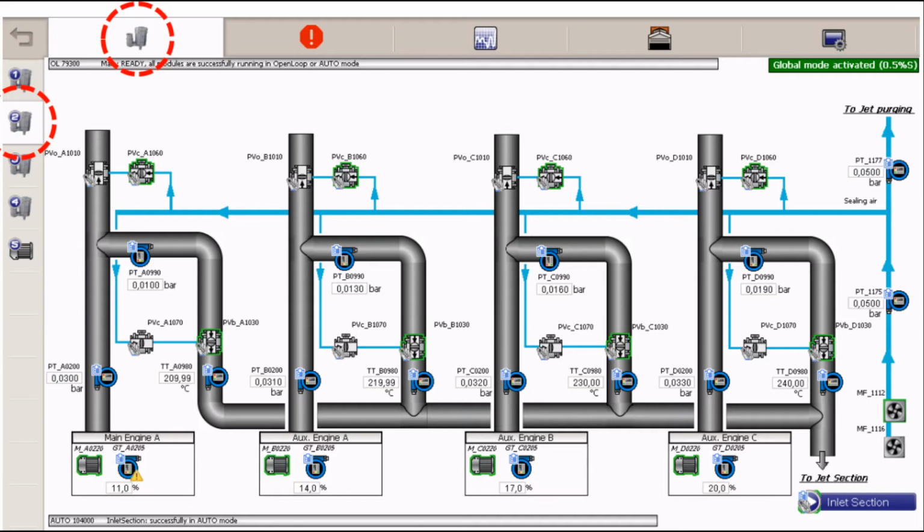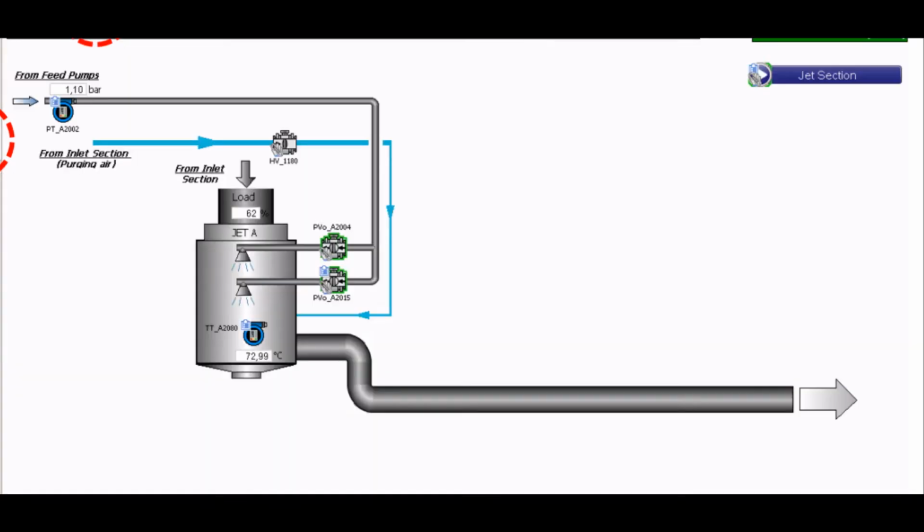The scrubber mixes water and exhaust gas thoroughly for maximum contact between exhaust gas and water. Process description of EGCS. When the bypass damper closes, the exhaust gas is led through the jet and absorber. The exhaust gas analysis system in the funnel monitors the quality of the cleaning process and informs the operator. The exhaust gas is cooled in the jet, where an initial SOx and particle absorption takes place.